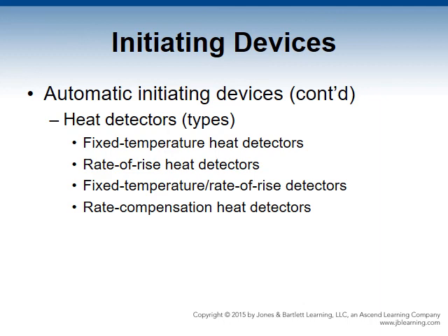The sensing elements are made with metal designed to expand at different rates. Once that metal expands, then the system connects and the alarm will go off. This method compensates for that thermal lag, and they are restorable.